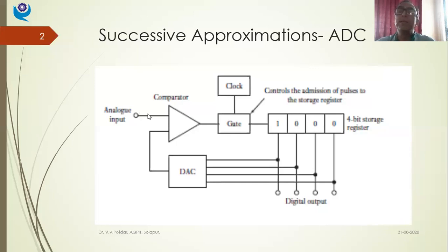Now, what is the input signal? Input signal is 8 volts. What is the feedback signal? It is 7.5. Okay. So in this cycle, the gate will still not allow the signal from the op-amp. Till what time? Till then, I'll keep on generating the digital signal: 7.5 volts, 7.6 volts, 7.8 volts, 7.9 volts. Accordingly, this signal will be fed here and will be constantly compared with the input analog signal. Presently, as I said, it is 8.